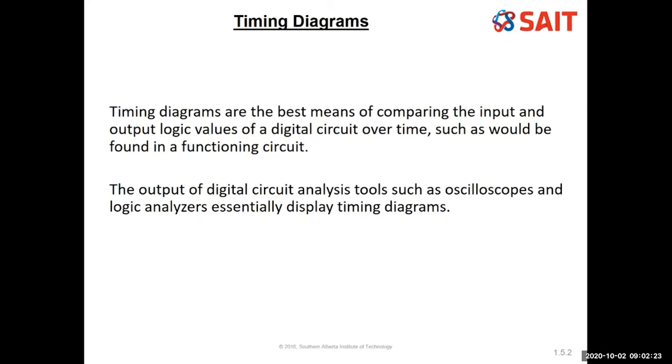When you buy a chip, a microprocessor that you're thinking of using in a board, the data includes numbers after numbers of timing diagrams in certain conditions, so that the person selecting it has a good idea of what the lag would be, or the delay would be, or how long the input conditions must be held before the output can be trusted, things like that. So a timing diagram is a common tool that we use in electronics.